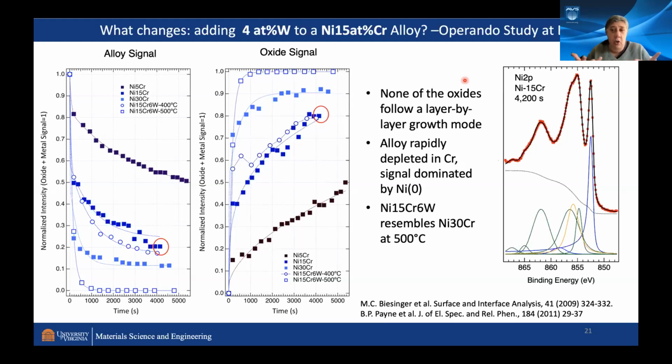You can now take the next step in the analysis. You can resolve the composition of the oxide, or you can also look very specifically and fit all of the nickel, chromium, and tungsten peaks. And we did all of that, but I'm just showing you here the fit of the nickel spectrum. And we followed here the prescription by Biesinger and Payne laid out in their papers. So we really do a very constrained fit here.